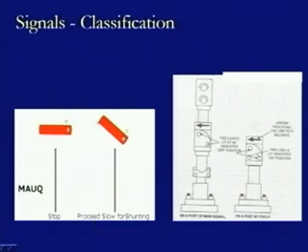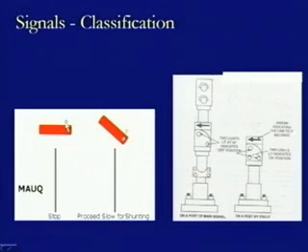That is one type of signal which you will find when your train reaches a junction, and at that junction we have the yards being provided. You can easily observe the small size of the signals provided on the side of the track, where there is a small post, and at the top of that small post the circular disc is provided. We can also see the holes. These holes define the color, which also defines whether the train has to stop or move slowly.